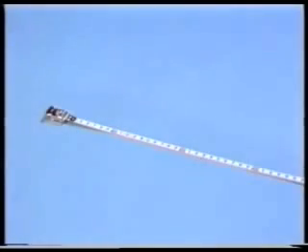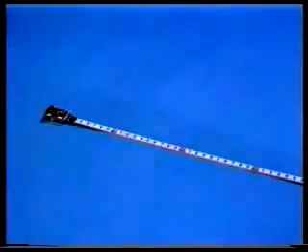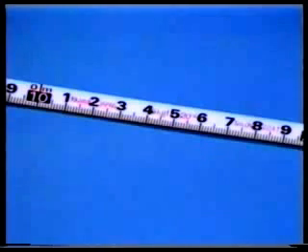The temperature correction is also only applicable to steel taping, and then only if high accuracy is required. Not only will the length of a steel tape change if it is pulled, it will also change if its temperature changes. To allow for this, when they are manufactured, they are calibrated at a standard temperature, usually 20 degrees C, and the value used is also written near the zero end of the tape.